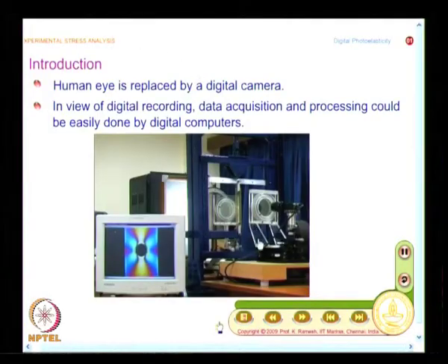After developing the methodology, I said you can also do it by processing the photograph in a conventional way, collecting data manually, but the method becomes advantageous when you go in for an image processing approach, and essentially aspects of digital photoelasticity. And what we introduced was, in digital photoelasticity, you replace the human eye by an electronic eye.